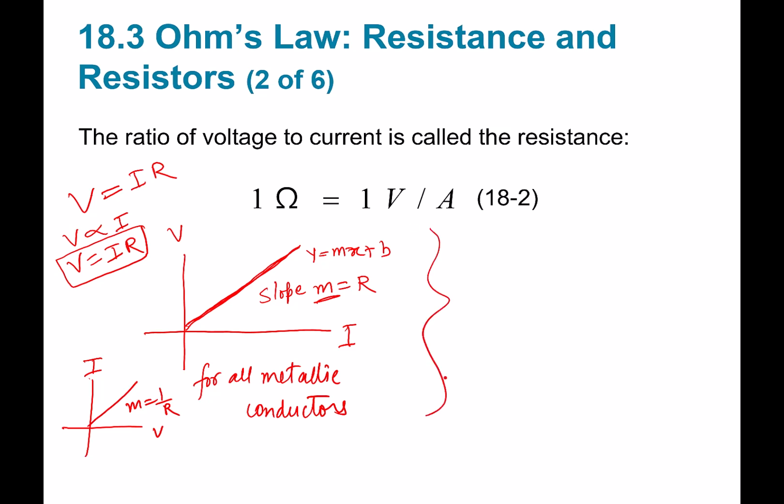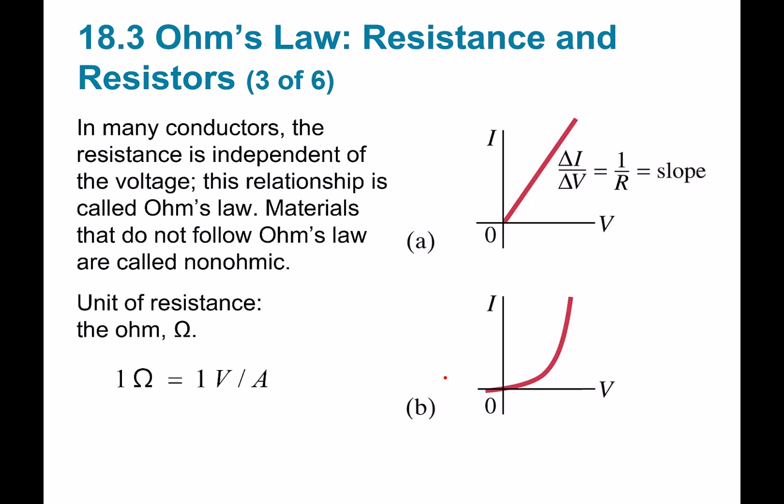Then there are different categories of materials that we call non-ohmic conductors. Non-ohmic conductors like LEDs, diodes. They don't follow Ohm's law. The current and voltage do not have a linear graph. So at a particular voltage, there's an exponential increase in the rise of the current. So non-ohmic device, like a semiconductor device, will not follow Ohm's law. You just have to remember that.